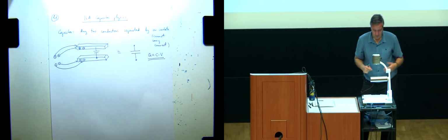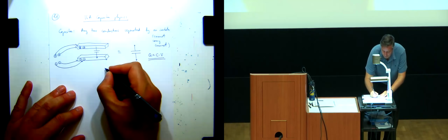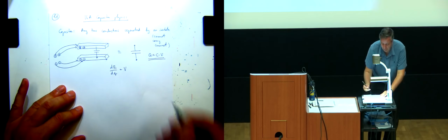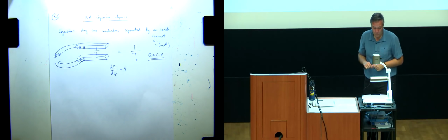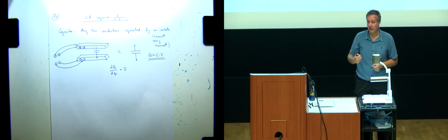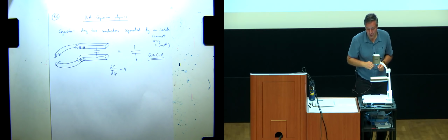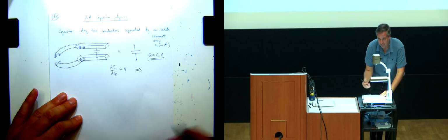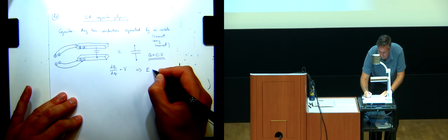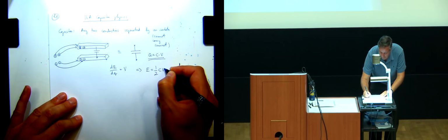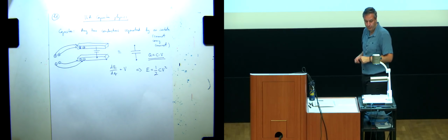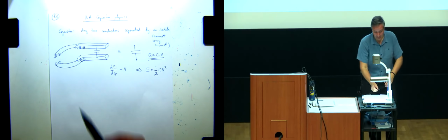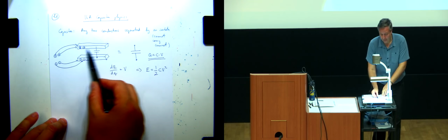In the notes, there's also a derivation based on this definition, right? That voltage is a chunk of energy dedicated for moving the charge. And so by combining these two, you can, again, practice calculus a little bit, and you'll figure out that the energy is equal to 1/2 CV squared. So that's the energy that we say is stored now in a capacitor simply because these charges are now populating the plates.